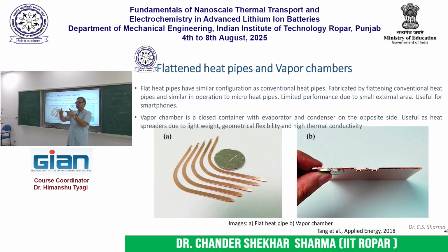The job of the vapor chamber is to spread that heat over a larger area so that it can be dissipated through the back surface of the smartphone to the outer atmosphere, thus maintaining the processor in its safe operating limit. And inside this vapor chamber, on one surface you will have the evaporator, and on the opposing surface you have the condenser with its own wick architecture.